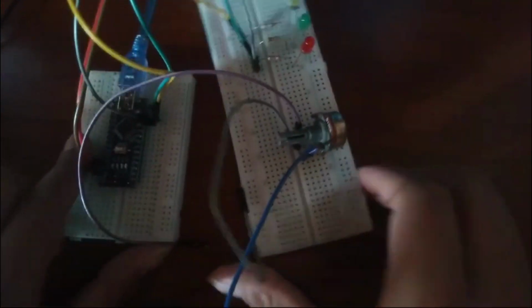Remember, it has to be firm. And once you have the connections, we're going to connect the other part, the middle pin. So this pin we're going to connect to A0. Remember that it is our analog input, right? So we have to search in our Arduino for the A0, right? So we're going to put the cables again. Remember, it has to be connected properly. Here we're going to connect the positive and the negative, as I told you. Yes, this is very important, because if you don't do this, it's probable that you won't have a power supply in your potentiometer, right?